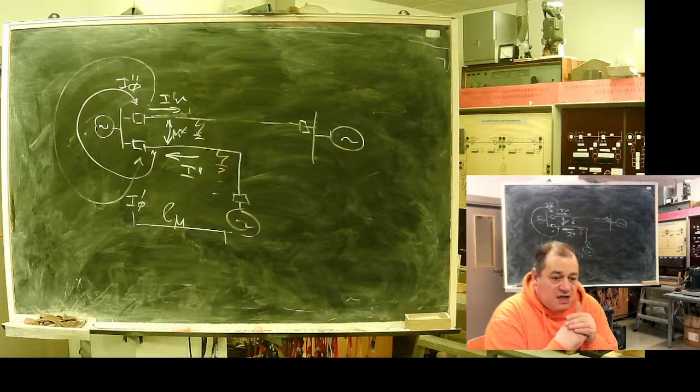For distance protection, it's normal to have a separate branch of algorithm for switch on fault condition. All the relays had a function: when the switch is disconnected, the time delay relay is activated. And on the connection moment, for up to 1 second, the time of the second zone is 0.